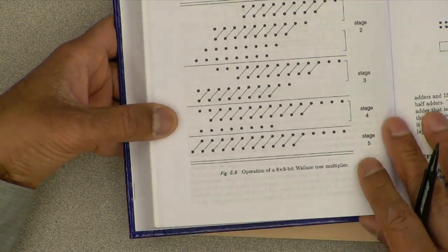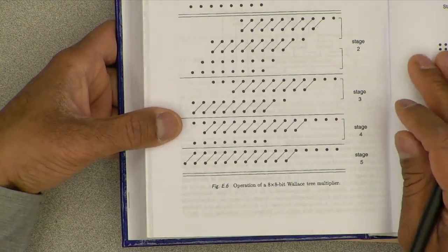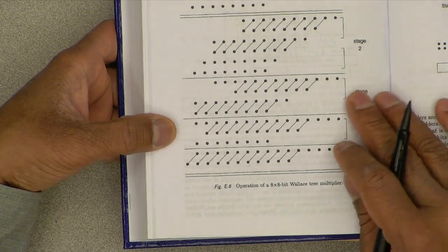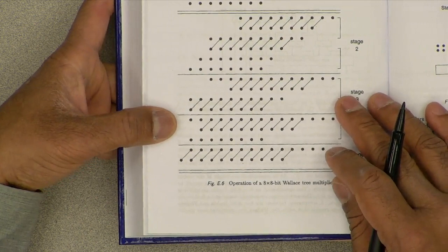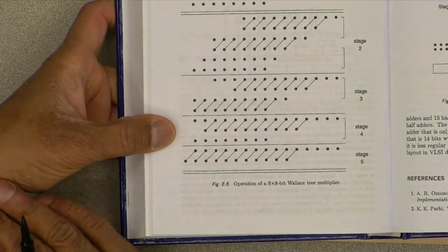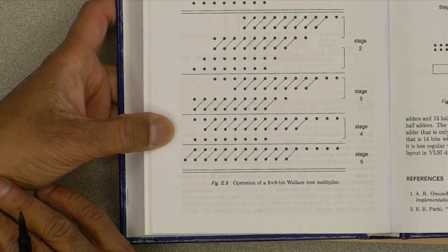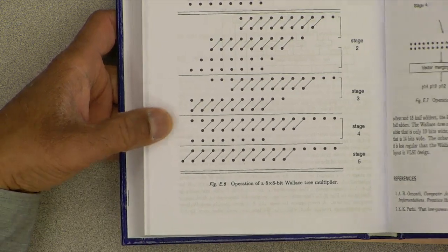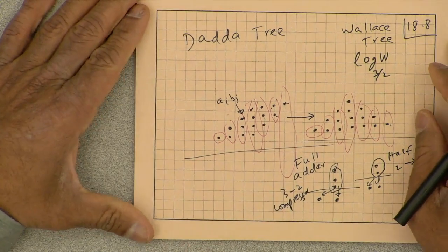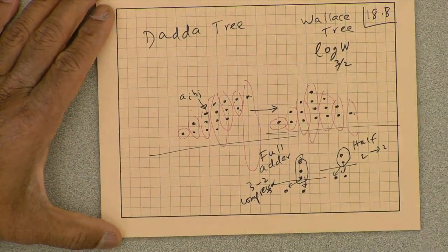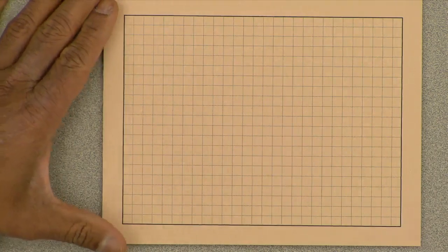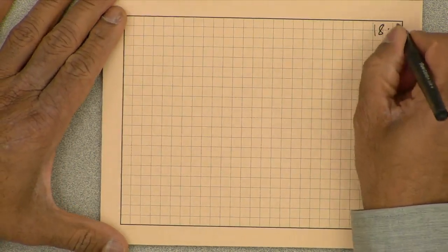So anytime you see a microprocessor or a multiplier in some GPU or CPU, all of those for many decades have been using Wallace tree and modified Booth recoding. Is that clear? Okay, so at least we have gone through the principles of Wallace tree and modified Booth recoding multipliers. Any questions so far?